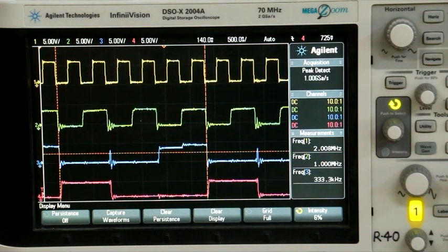So therefore, commonly ripple counters are not used beyond a particular frequency. Let's say a few megahertz is not used. So right now we are talking about roughly about 2 megahertz, and you can see this is very prominently seen, which can create trouble.